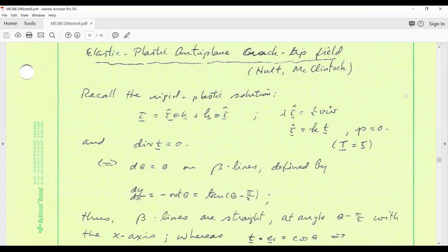Why linear elasticity? Simply because it's tractable. And it has a very well documented empirical basis. And so what people do in fracture mechanics is they push linear elasticity beyond its intended limits and simply live with the contradictory conclusion that the stress and the strain become unbounded at a crack tip. And of course, that's unsatisfactory.